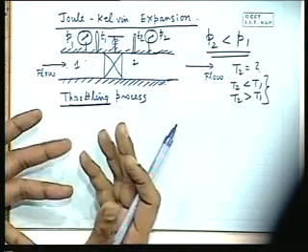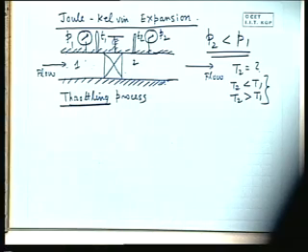We don't know the extent of decrease in temperature. That depends upon the typical equation of state. And at the same time, because some fraction of the pressure energy, a part of the mechanical energy, is being converted into intermolecular energy, temperature should increase. So these two countering effects decide which one will dominate over the other, so that there will be either an increase or a decrease in temperature. Under usual conditions, our common practice is that whenever you throttle a fluid so that its pressure is reduced to allow it to flow through a restricted passage, usually the temperature also drops, but it is not always the case.